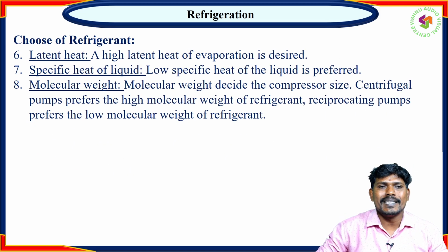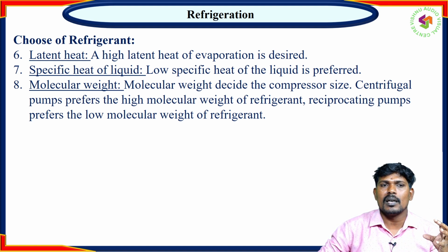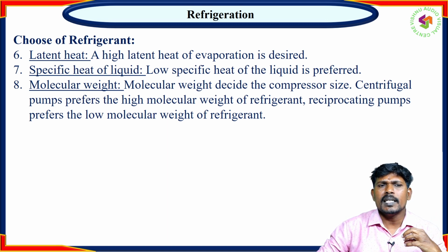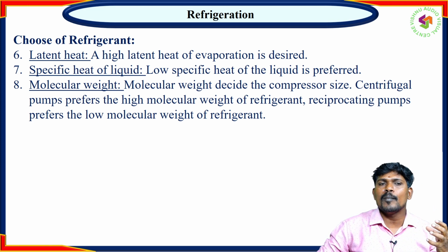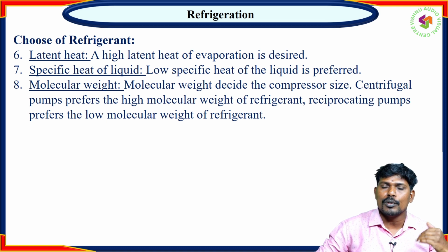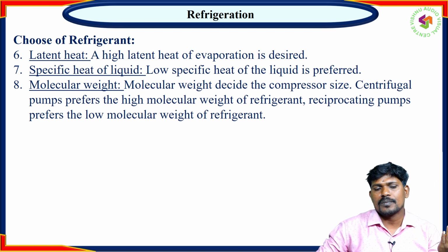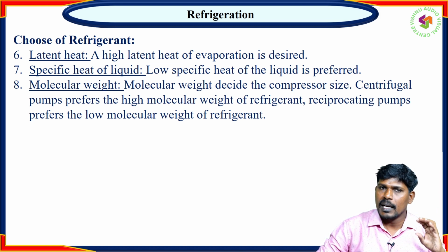Next one is the latent heat. Latent heat is the minimum heat required to change its phase. For example, water is there, you are supplying the heat to the water. So initially the temperature rises. After 100 degrees centigrade, however much heat you supply, the water maintains 100 only. Means whatever the remaining amount of heat is, it is converting into latent heat, so that the phase is changed. So here the latent heat of your refrigerant must be high.